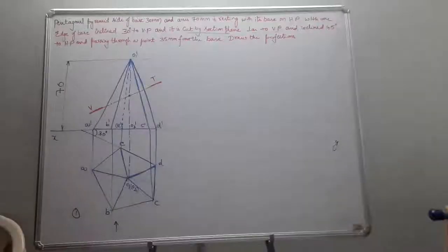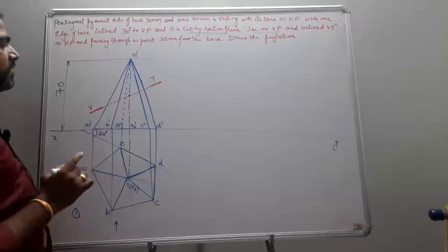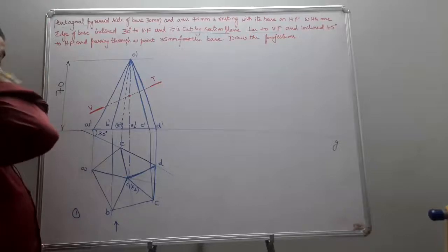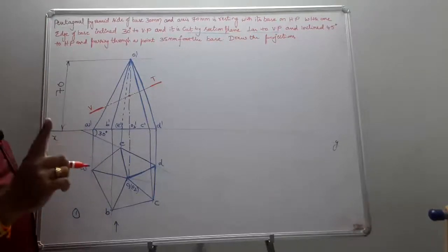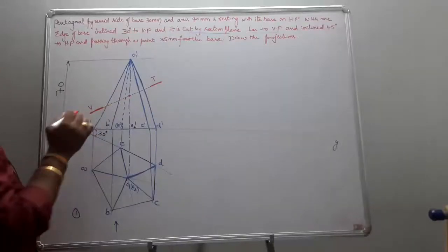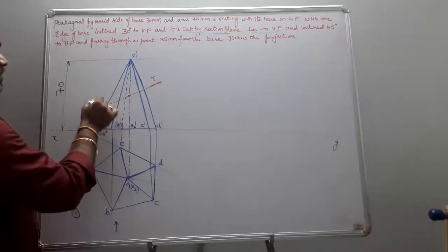Now, all of you tell me the numbering. I didn't directly put it for you. First of all, you just see this. I just make you answer the points which are going to be obtained where your cutting plane cuts the solid. First step is always stand on the extreme left. So this was the extreme left. Always give preference first to the solid line. So this is going to be one of the points. This is 1.